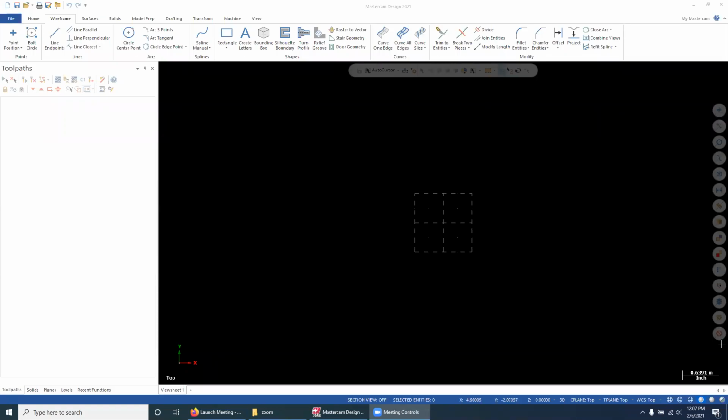Hi, in this video, I'm going to be demonstrating the 2D slot milling toolpath in Mastercam. So I'll be sticking to utilizing the outline for those 4-inch by 2-inch by 1-inch blocks. So using the outside geometry of that rectangle, and then in the middle, placing an ob round, so a rectangular ob round in the middle. And then doing a slot mill tool path for that to cut the ob round out.